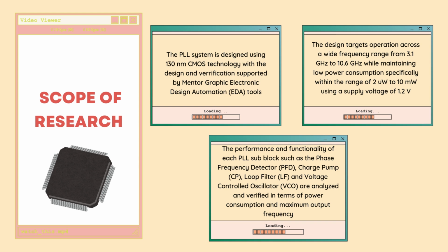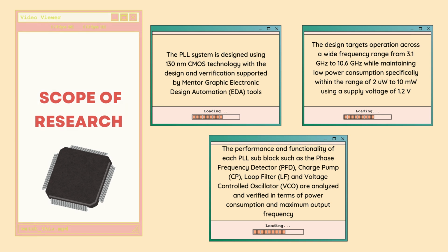And lastly, the performance and functionality of each PLL sub-block, such as the phase frequency detector (PFD), charge pump (CP), loop filter (LF), and voltage-controlled oscillator (VCO), are analyzed and verified in terms of power consumption and maximum output frequency.